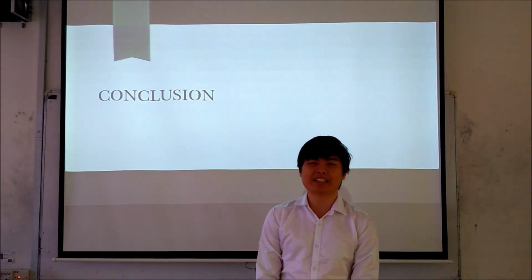Lastly, I will conclude this presentation. Although glycerol carbonate is a very promising product with high market value and various usage, its high cost of production makes its development rather slow, and it's only due to the reduction in glycerol's price that glycerol carbonate research kick-started. Usage of calcium oxide as catalyst boosted the conversion rate to 100% with residence time of 90 minutes. In terms of costing, most of the cost goes to pretreatment, and the total production cost amounts to 7.635 million.